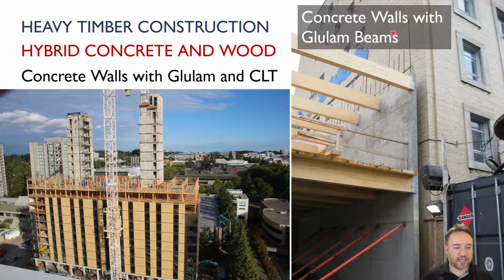But in order to get some of these early projects like Brock Commons, which is the same building we talked about earlier on the left, through approvals, in order to be able to build a huge, tall timber building like that, they decided to make the primary core, lateral load resistance, and emergency egress out of concrete walls. So then there's no question about how well this structure will perform.